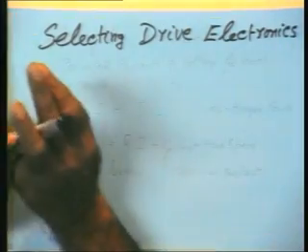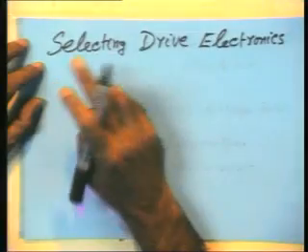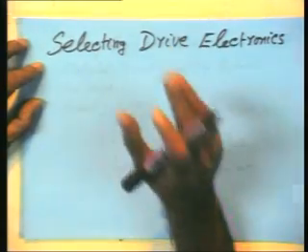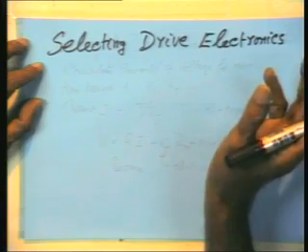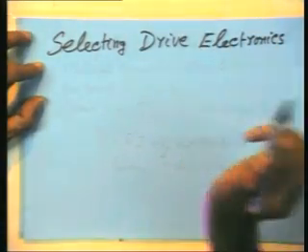Now yesterday I had shown you how to calculate the various torques, the continuous, the RMS value and the peak value. We had seen various segments of the motion, incremental motion, the acceleration segment, the deceleration segment, the uniform velocity segment, and individually we had calculated the torques as T1, T2, T3 and T4. Based on that we had selected the motor in the previous class.